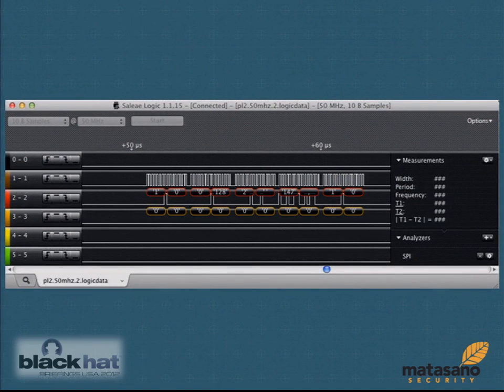After reading all this and understanding more about SPI, zoomed in, you can tell that brown number 1 is the clock pin, and it's going at 16 different ups and downs through each blob. Then the next one was the master output, and the following one was the master input. Again, you can see the bubbles representing the data above them. In this specific configuration, I had it at 8 bits per character, which is the default. However, it could be 16.